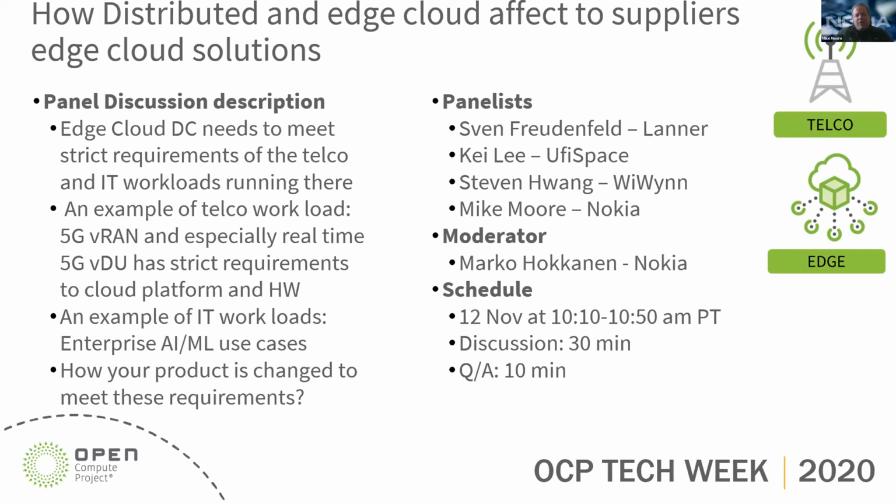And so Nokia continues to invest in OpenEdge. We continue to make contributions. We're currently in the process of contributing a 2U chassis. We're contributing a switch design that also has precision timing, PTP, included in it with GPS input and double ovenized oscillator for extended holdover times. And we are committed to creating edge-based hardware platforms.